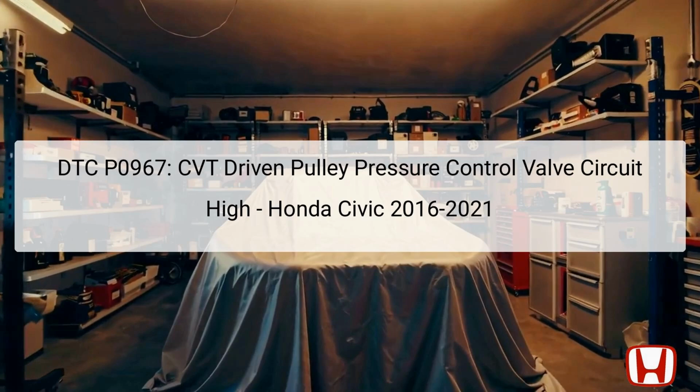The DTC P0967 refers to an issue with the continuously variable transmission, CVT-driven pulley pressure control valve circuit. This valve is critical for regulating hydraulic pressure within the transmission system of the Honda Civic models from 2016 to 2021. It operates under the direction of the Transmission Control Module, TCM, which uses feedback control to adjust the hydraulic pressure based on current inputs.